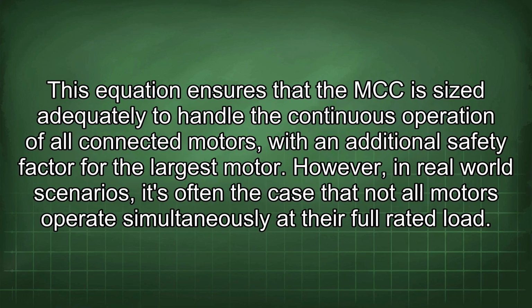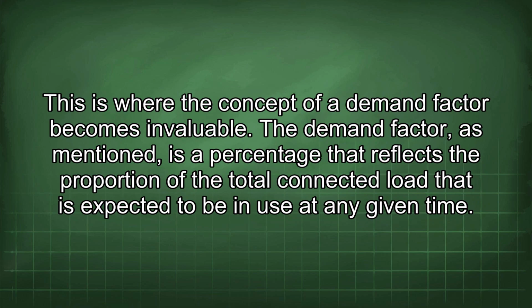This equation ensures that the MCC is sized adequately to handle the continuous operation of all connected motors, with an additional safety factor for the largest motor. However, in real-world scenarios, it's often the case that not all motors operate simultaneously at their full rated load. This is where the concept of a demand factor becomes invaluable.